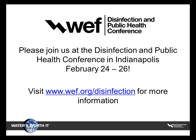And then, was there a reason you went with the low pressure, high output system versus a medium pressure system? That I'm trying to remember. I don't remember exactly how it came out, but it worked itself out. We all agreed that seemed to be what was going to be the best for us operationally here in Jeff City. Yeah, so there was probably an interest in the longer lamp lives of the 12 to 13,000 hours compared to 8. Correct, and even now, even when we started looking at this a couple of years ago,